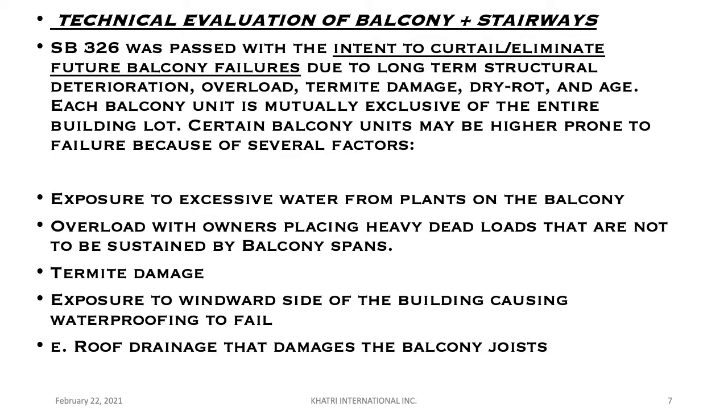So one key thing to draw from this first paragraph is that each balcony unit is mutually exclusive of the rest of the building lot. In other words, you can't really say that if we have 100 balconies at a building, that if we inspect 10 of them, that we can conclude that the other 90 are going to be similar. I take a different position on this perhaps than other engineers.